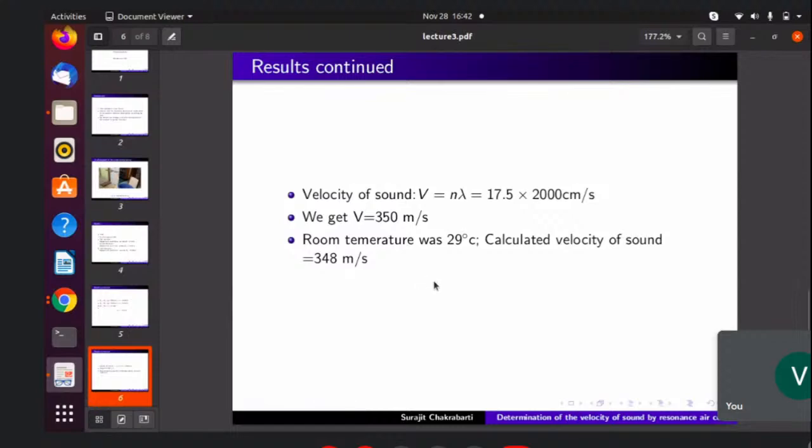So the main part of this experiment, the difficult part, is setting up of the mobile phone if you don't have a stand. And a more difficult point is how to drill a hole at the bottom of this. This is the most difficult part. I don't suggest that you do it right now, because you are doing experiments for the first time. Maybe you can seek some expert help. Maybe the vendor who is supplying you this cylinder, you can ask him to drill, not exactly drilling. There are some other things by which you can do this. About a 1 millimeter diameter hole.